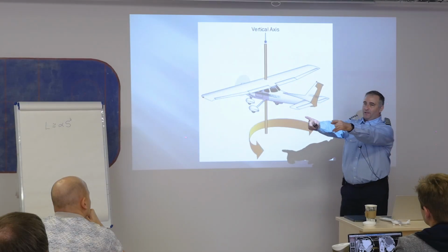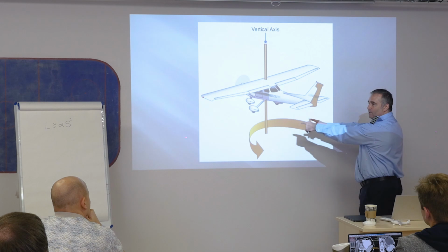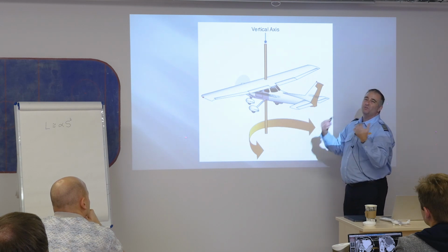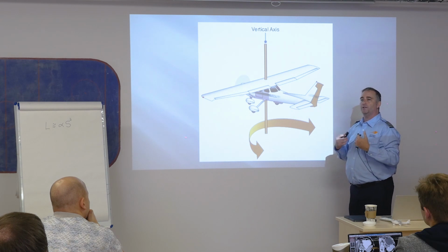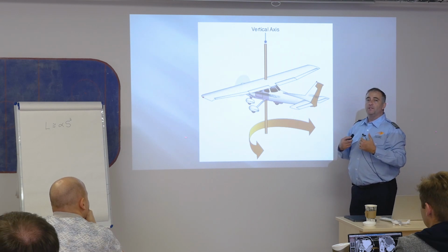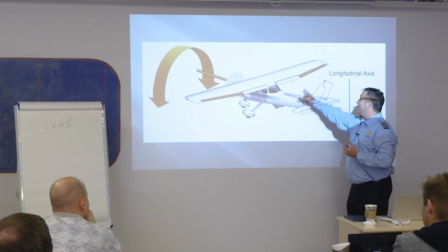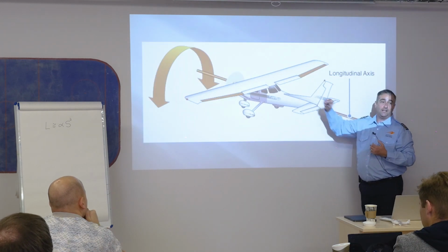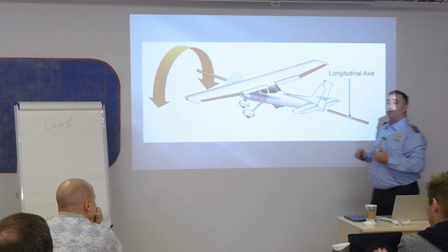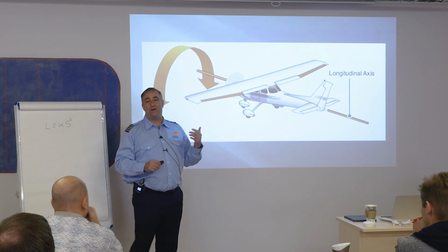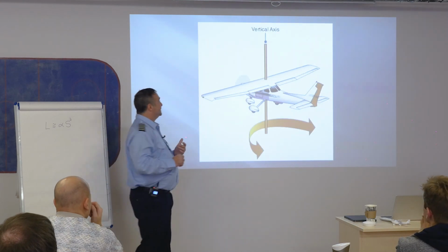But if I have a little bit of left or a little bit of right, it's imbalanced. It's not balanced properly. It doesn't really feel comfortable for the passengers either. Okay? Some of these things will happen as a natural phenomena of using your ailerons. That's called adverse yaw. Okay? And it's one of my favorite things to make sure that pilots know before they solo.